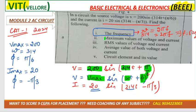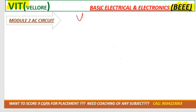Now in the next part they have asked the maximum value of voltage and current, which we already calculated by comparing the equation. Vmax is 200, Imax is 20, right? Now in the next part they ask you the RMS value. I told you the formula: VRMS is equal to Vmax divided by root 2.